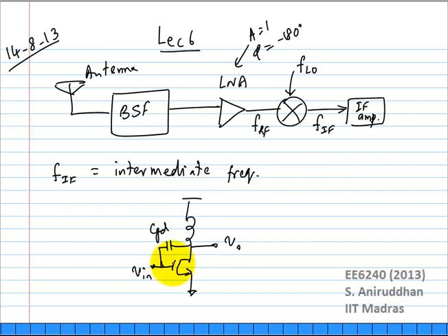Okay, normally if you take an LNA, a low noise amplifier, you don't have to worry about this, because the device sizes will be pretty small. The cases where you have to worry about it may be in a power amplifier. It's still ideally an open loop system, but because the devices may be several millimeters large, you will have a parasitic CGD, which could lead to stability problems. Normally in an LNA, it shouldn't be a problem. You will still need to check, but it shouldn't be a problem for a well-designed LNA. Okay.